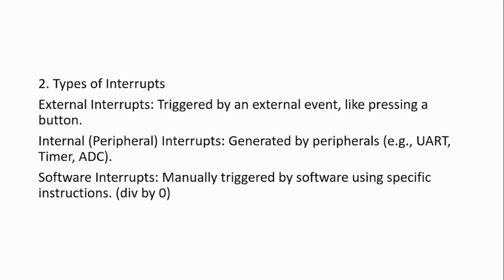Second is the internal interrupt, where it is generated by a peripheral like UART, timer, or ADC. I will cover this. Here the interrupt will be generated by these internal peripherals themselves. And third is a software interrupt. A software interrupt is manually triggered by software using a specific instruction.